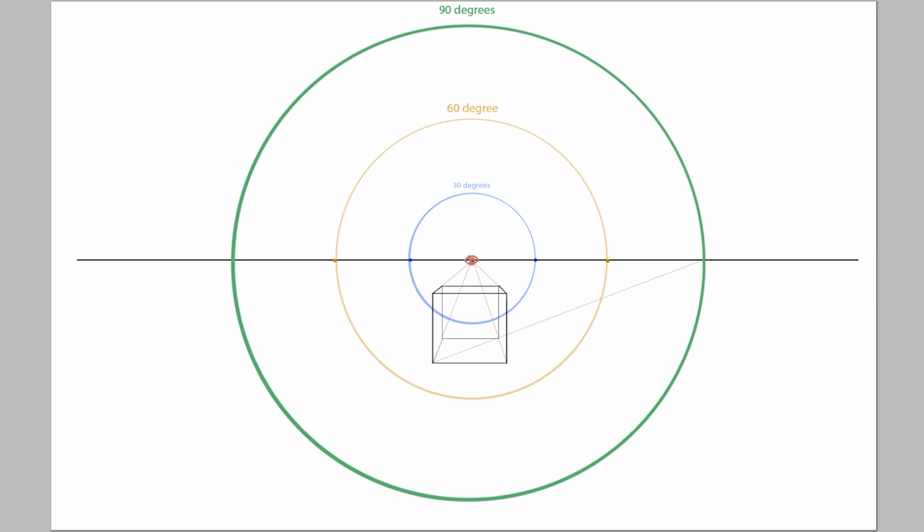At this point, you may notice that I'm ignoring the overlap rule at this stage in the drawing, almost drawing the cube as though it's made of glass and I can see through it to the back lines. This is a very important point in how we're going to approach drawing in this way. It is important that you understand how to perceive the unseen side of an object. So as we move forward, I want you to, as much as you can, draw in this X-ray manner in the early stages of the drawing.